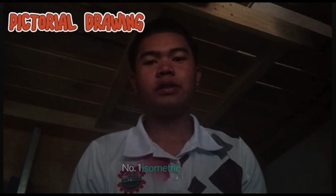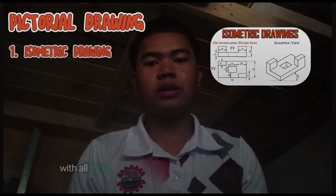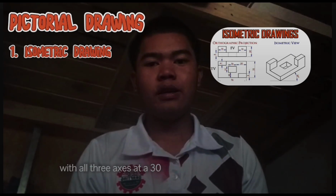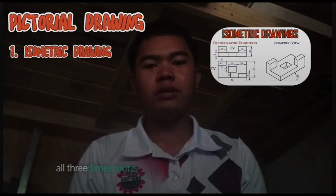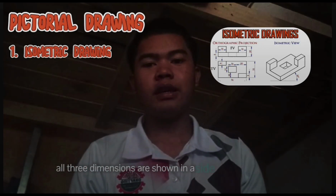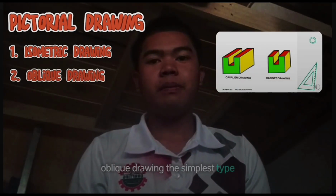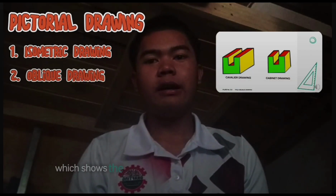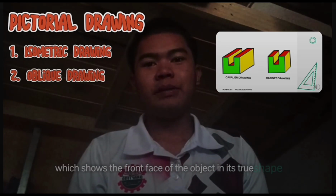Types of pictorial drawing. Number 1, isometric drawing. It shows 3 faces of an object with all 3 axes at a 30-degree angle to the horizontal plane. All 3 dimensions are shown in a single view. Oblique drawing is the simplest type, which shows the front face of the object in its true shape.